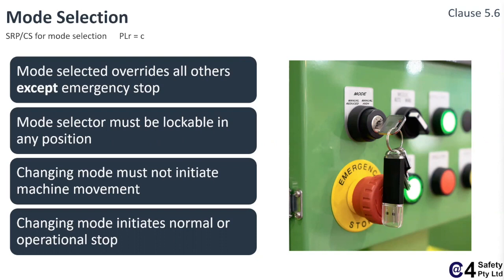Now we've got a key operated one there. It doesn't have to be key operated. I've seen ones using RFID tags. I've even seen ones using codes and passwords. Not so keen on those because those passwords tend to be on Post-it notes next to the machine. And I know you've deliberately done another thing here again to pick up the issue of people leaving the key in the selector switch mode. I very well selected that image there.